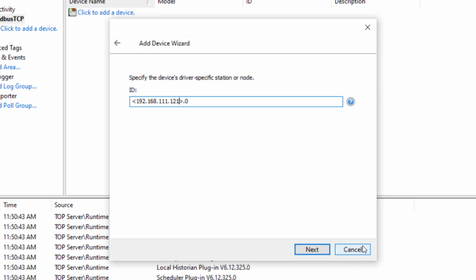While a non-zero bridge index should technically only be used for devices connecting to a Modbus TCP to serial bridge, it is not uncommon for device manufacturers to still use a non-zero device or node ID. In that case, you would need to make sure and specify this as the bridge index in addition to the IP address. It is possible to configure the server to act as a Modbus server or unsolicited device.